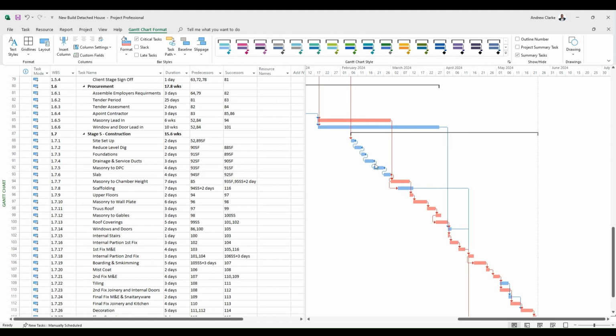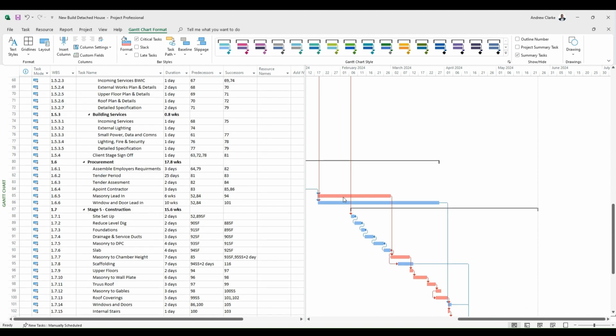You can see these links go backwards. I've turned that around on the link so it's a start finish. If we started these as soon as possible, you're going to start and then be waiting around to get material, and you see that quite a lot, and mistakes. It's always worth knowing what your constraints are, knowing your critical path, and then working back for your starts on site.